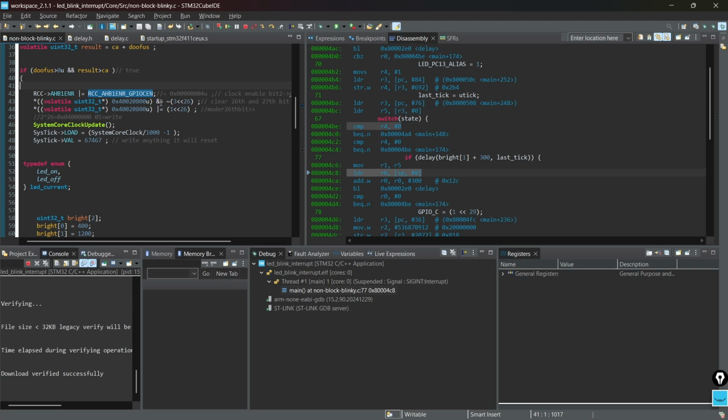we clear the mode register. 3 is just 1 1 in binary, and logically shifting it 26 places, and then taking the complement, and then using the AND operation means we are clearing the 26th and 27th bits.